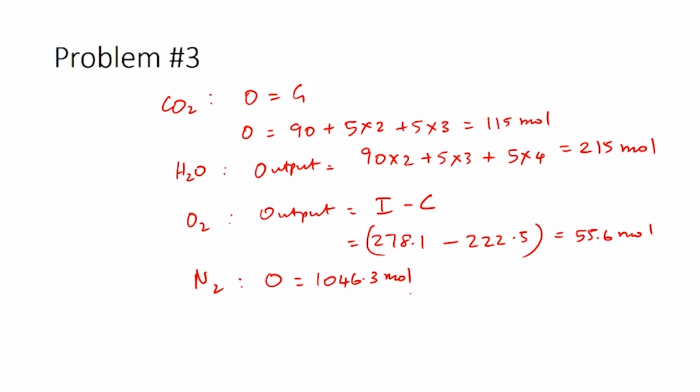We know that this stack gas is coming in at 1000 degrees Celsius. So, now our next step is to perform the energy balance calculations for the waste heat boiler. So, since all these gases are combustion gases, we can actually use tables from the textbooks or from reference books where we can get information about the enthalpies for these gases. Table B8 in Felder-Rousseau, which is one of the prescribed textbooks, actually has these values, and we can directly use them for performing these calculations.